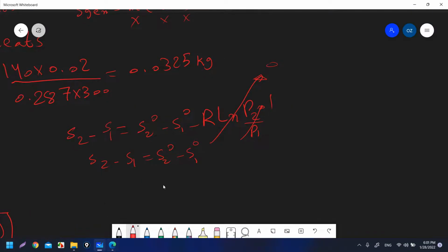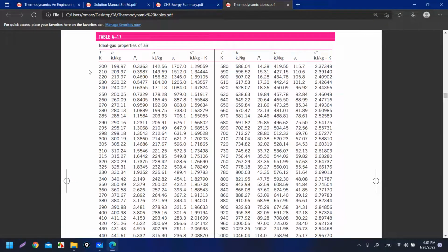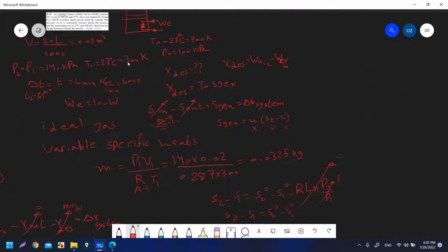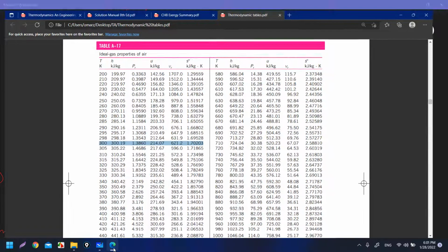Okay, so here, what was T1 or P1? We don't have pressure in this table, so you need temperature or these other properties. He gave me in the question that T1 is 300 Kelvin. So on this line, at 300 Kelvin, S naught equal to 1.70203.